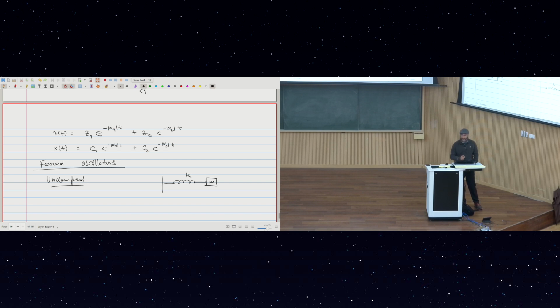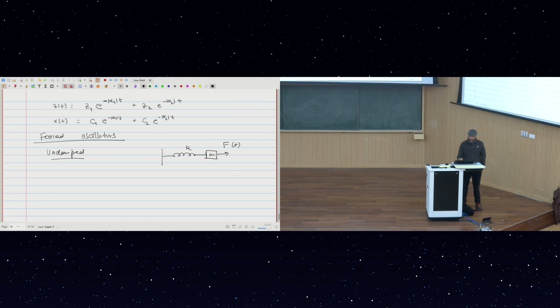So we have a spring mass system, but in this case we are applying a force to the mass, and this is a function of time. There is no friction, there is no damping in this case. And force is a function of time, so how do we proceed? We'll have to start with some nature of this oscillatory force. We'll call it a harmonic force, which is F naught cos omega t. F naught is a constant, and omega is the frequency of forcing.